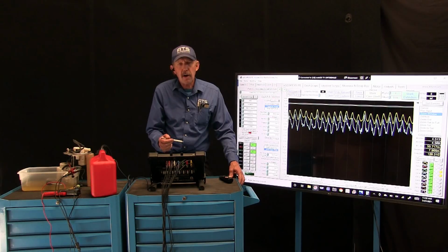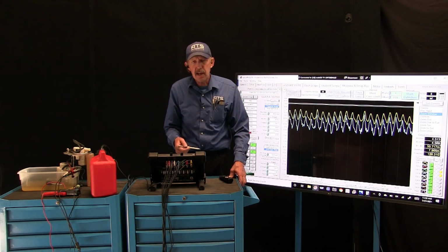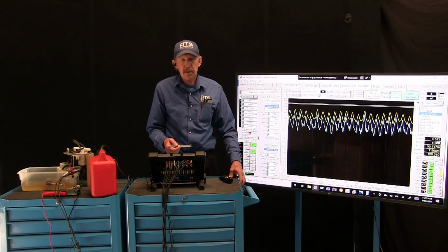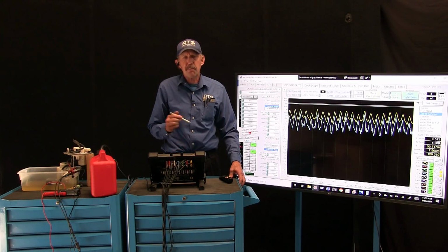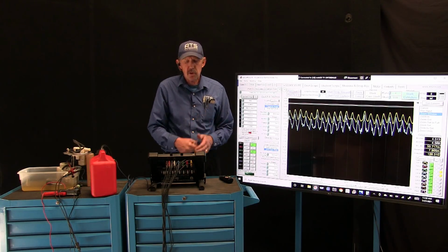Now on the car we're working on, we saw the pump slow down when I dropped pressure, not speed up. But now that we understand some basic principles, we know that it has to be restricted, because if the pump doesn't take off, the pump is still seeing the same pressure. It's not changing pressure because it's pushing against a restriction.